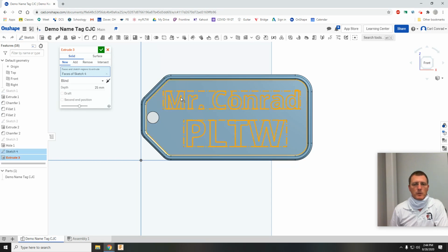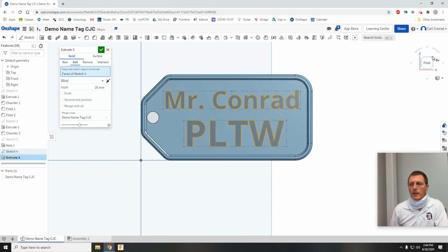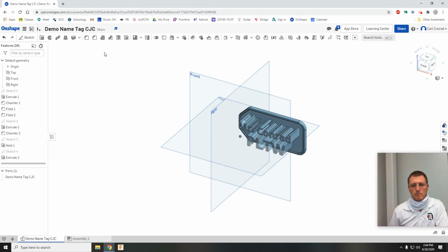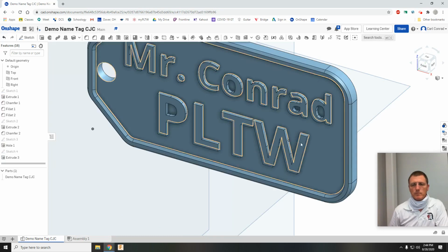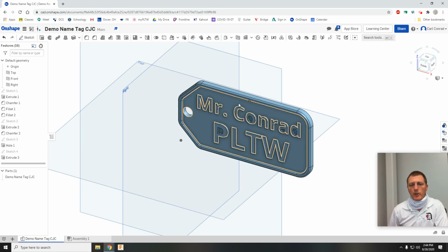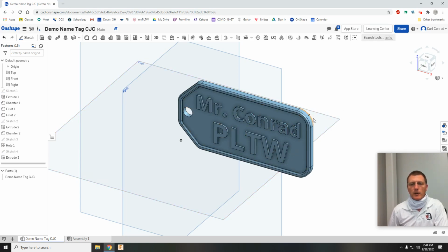you can extrude, and we want to extrude that text a height of 1.2 millimeters. Okay, so it may take you a little while to get your text to look centered and visually look good, but once you figure out the numbers you need to dimension and get it where you want it, go ahead and extrude that and get it set up.